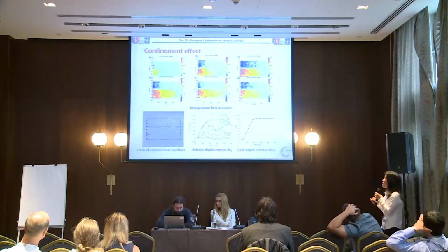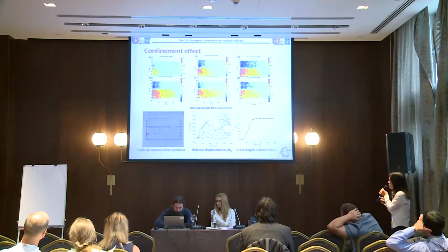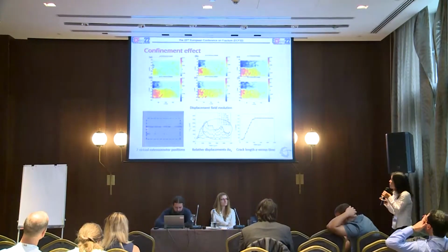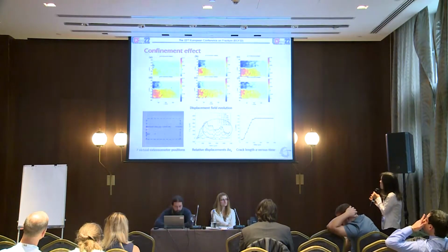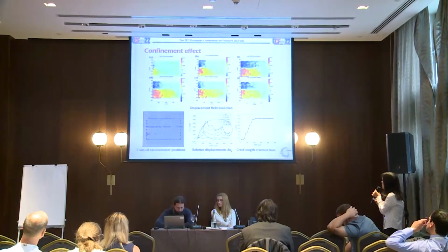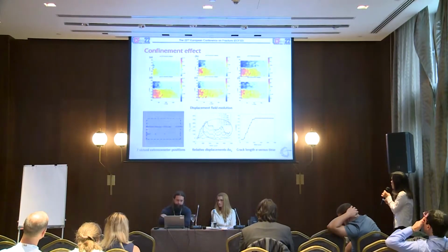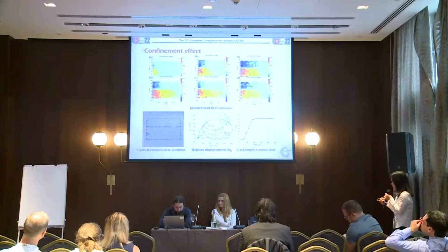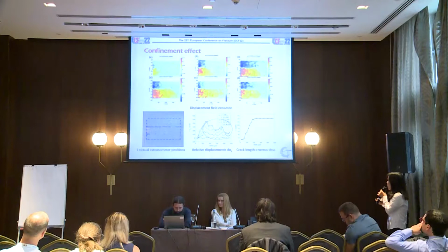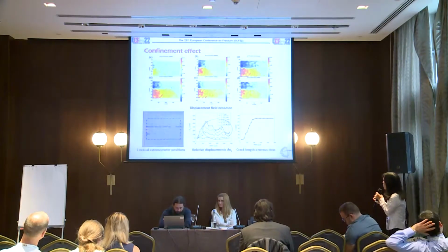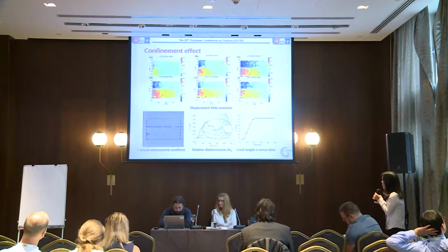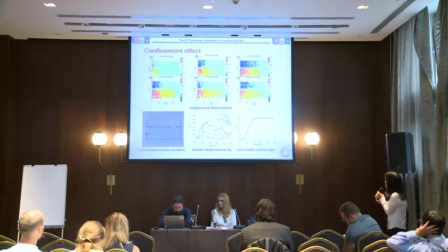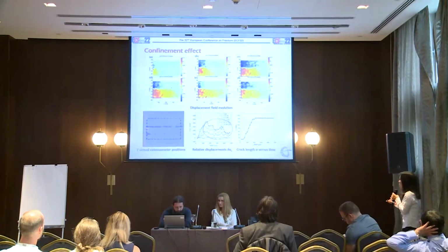Next is the confinement effect. The displacement field here is a little different from the figures before. You can find that in the loading process, the opening displacement first increases, but when it reaches maximum values, it does not increase anymore, and crack arrest happens.